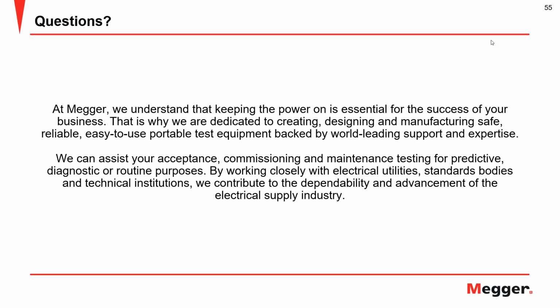Now there are several other ways of testing. Specific to cable, one that's common is online testing through HFCTs. The advantage there would be that it's an online test, I suppose. But there are different applications for different measurements. UHF was mentioned. UHF is a common measurement for GIS partial discharge, and that just happens to do with the gas physics there, and I won't get deep into that. And acoustic measurements are used for location of PD.